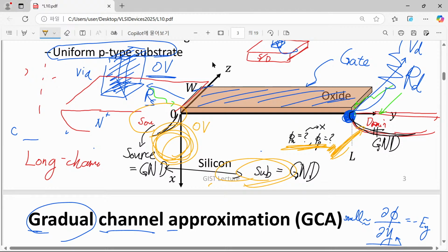When you have a PN junction, your hole quasi-Fermi potential is almost constant all over your p-type region, and even for the depletion region; only in the minority n-type region your hole quasi-Fermi potential changes. On the other hand, if you consider electron quasi-Fermi potential, inside the n-type region and depletion region, there is no change in your quasi-Fermi potential. Only inside the p-type region, the quasi-Fermi potential changes.